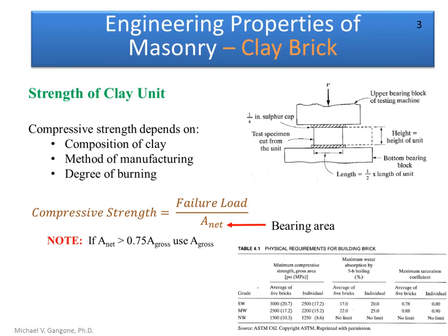This is the net area, and it really depends. When you have your masonry unit, this is, say, a top view of that unit, and maybe you have a couple of core spaces or cavities in that particular unit. The net area is basically all the area that does not include the empty cavities, and the gross area is the entire thing, the whole area including the empty cavities.